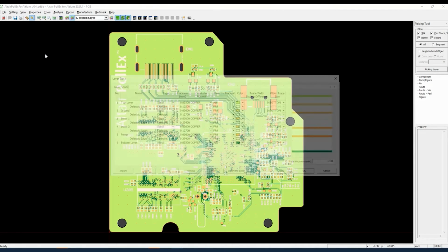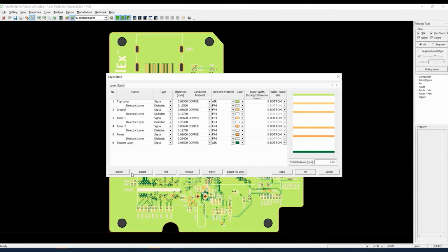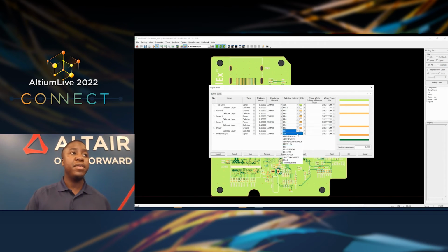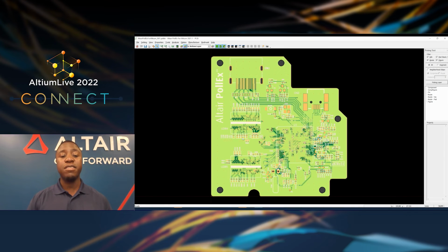We'll also look at adding and adjusting our layer stack up. We can think about if we were to use our thermal test to figure out if we're going to be able to use a thicker copper, or if we can actually get away with using a thinner copper, a 1 ounce as opposed to 2 ounce. That could save us overall cost, especially at building large volumes.